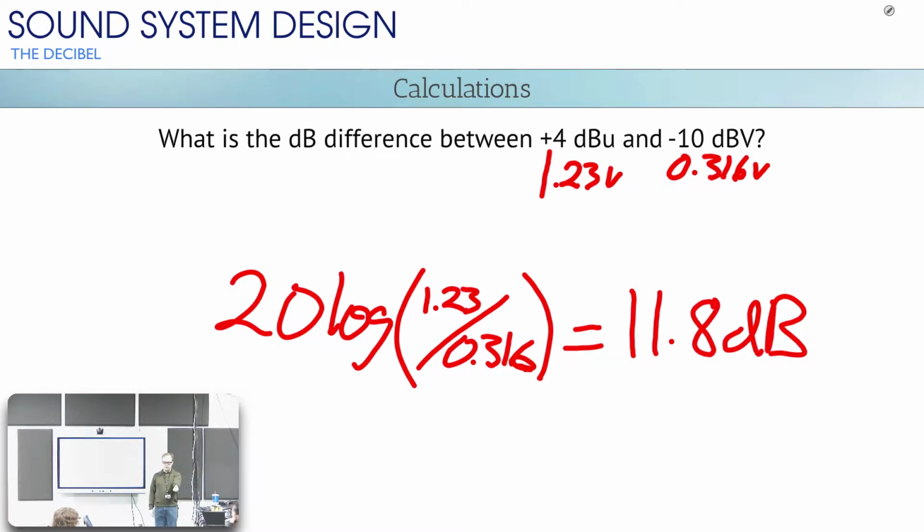input gain. So I would know that right off the bat, whatever input is listening to that consumer level CD player, I've got to turn that up 12 dB no matter what, because it's going to put out a 12 dB quieter signal than the other CD player. Okay? So if you know that, then you can correct for it. Yeah? Okay.